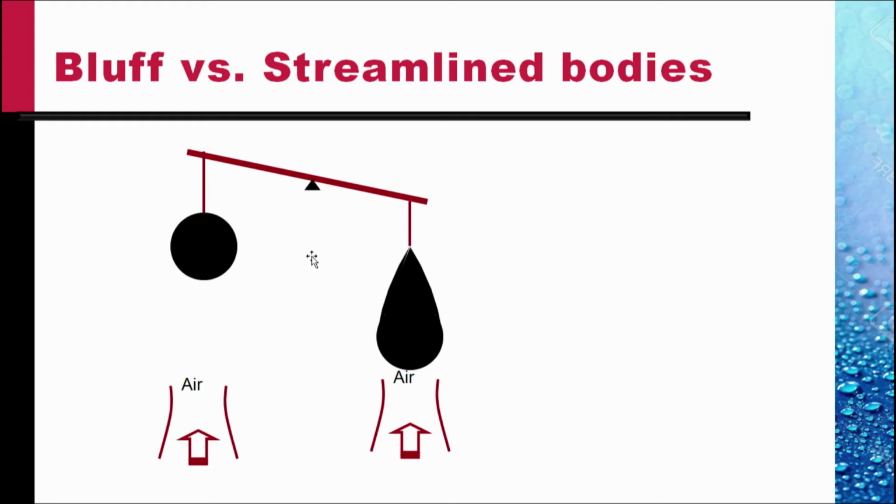On the other hand, on the sphere, we have shown just now, the flow separates before the equator, and the pressure at the back of the sphere does not recover to the values in front, and that leads to large drag of the order of pressure forces.